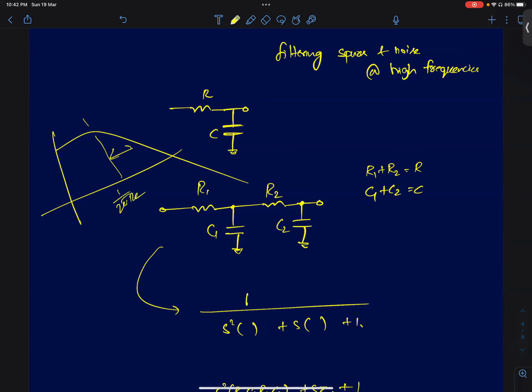So if, let's say, you're concerned about noise at some specific frequency, you can choose the pole frequency in such a way that you get sufficient attenuation. Because that's a classic filter design problem. But in analog circuits, area is the most important thing to keep in mind. You can't just arbitrarily keep putting as large a filter as you want, but area usually restricts how much filter you can have.